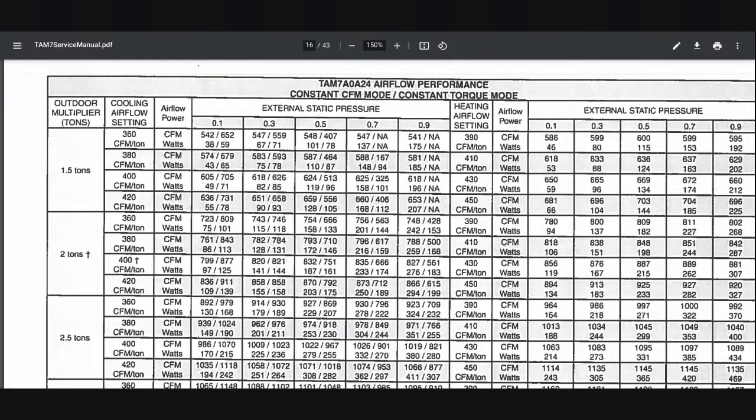Now, that's if you wanted to find out the CFM. I talked about the fact that I really want to make this simple. Most of the time, unless you're trying to balance something or achieve a very specific goal, there is, and you have to be careful with rules of thumb, but there is a little bit of a rule of thumb with these low static systems, as I'm calling them. And that is, a healthy system is going to run below 1/2 inch of static.